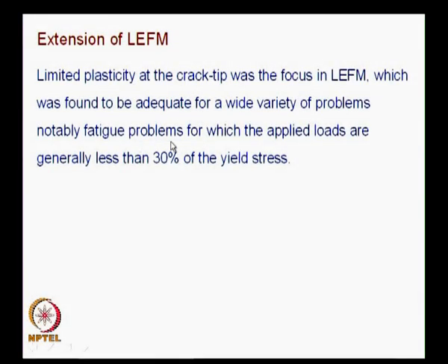notably for fatigue problems, the applied loads are generally less than 30% of the yield stress. So, you are talking of structures which are loaded far below the yield stress, and you are confining your attention to high strength alloys, and LEFM was sufficient. And this was possible because you had only limited plasticity at the crack tip. As design requirements expanded, this kind of analysis was not found to be sufficient.